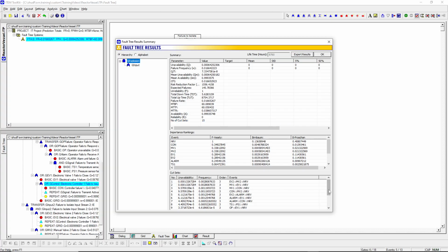Why did this happen? By introducing the grid variable across our automated safeguards, we have created a common cause failure path. Our initial, highly robust redundancy between electronic valve 1 and electronic valve 2 has been compromised. The shared power dependency generates entirely new combinations and pathways for the automated system to fail. However, notice that this structural change has not impacted our human protection layer or our mechanical relief valves, which remain completely independent of the electrical grid.